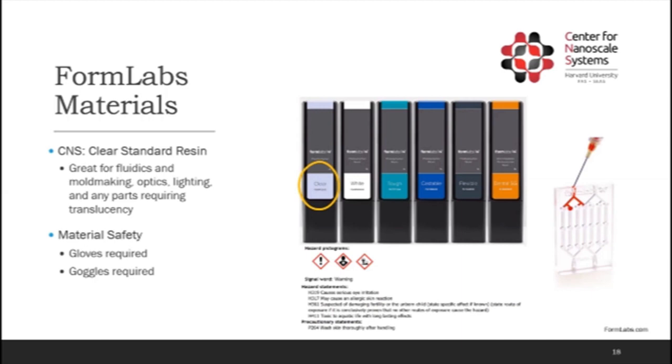And I do want to mention that the uncured liquid resins that SLA printers use are toxic to your skin. They do have a safety hazard warning in there. So gloves and goggles are mandatory when handling any sort of SLA printer.